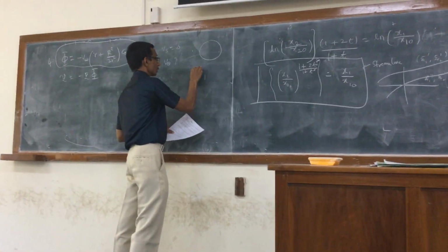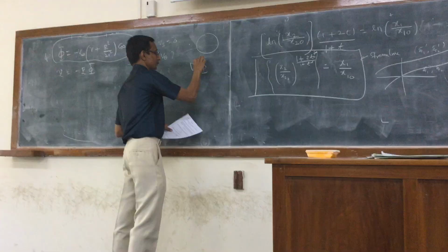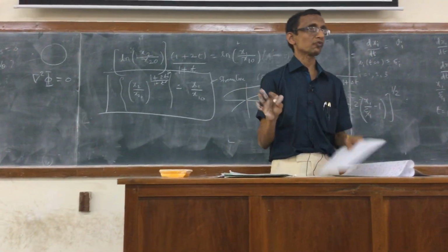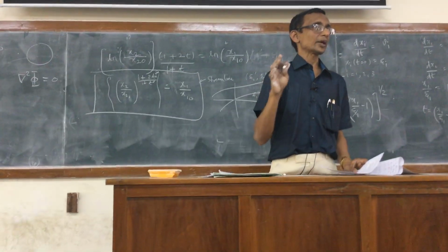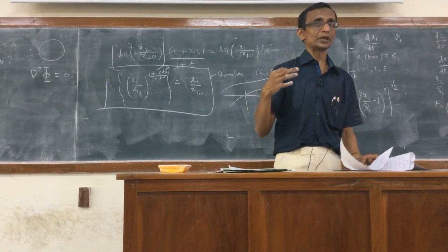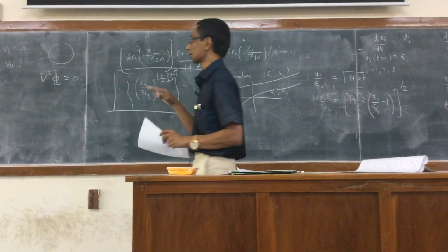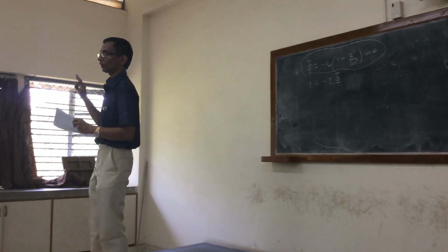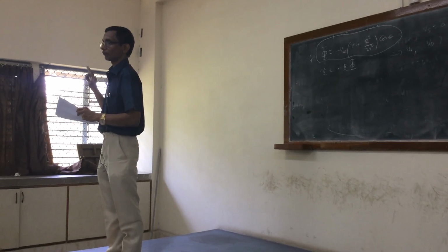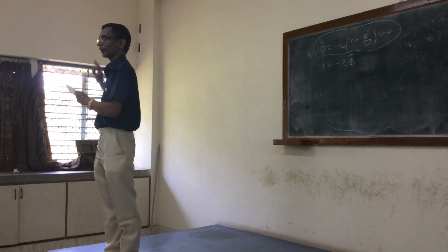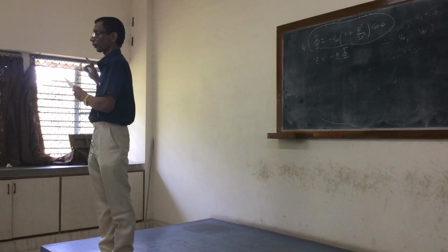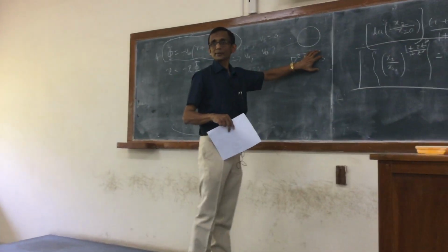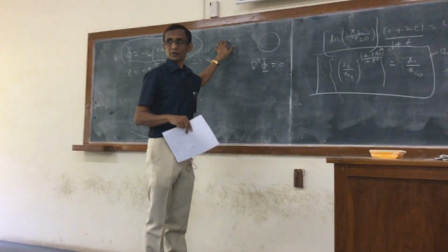But anyway, the important thing to recognize is that this is the same for all irrotational flows. The particular geometry, the particular dimension, here a two-dimensional case, will determine what the final expression is. The boundary conditions will be very similar to what we had. So this is the exact analog of the cylinder problem which we have solved. It will be worthwhile for you to actually solve this Laplacian equation because the answer is given.